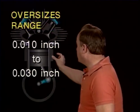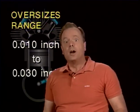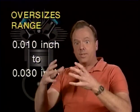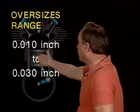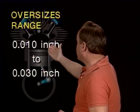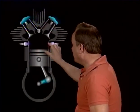Now, car cylinders can go oversized up to 100 thousandths of an inch, but airplane cylinders cannot go oversized that much. Why? Because the walls between the cylinders are very thin, and another reason is that they sometimes are nitrided. You don't want to take away the nitriding. So aircraft cylinder oversizes range only from 10 thousandths of an inch to 30 thousandths of an inch, whereas a car could be much more than that. And they want you to know the 10 thousandths to 30 thousandths of an inch on the test.